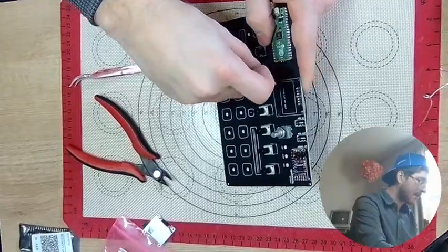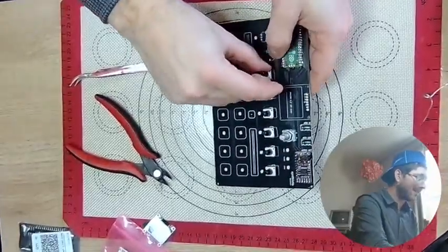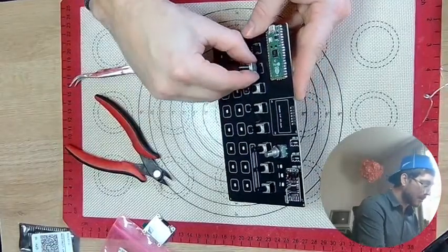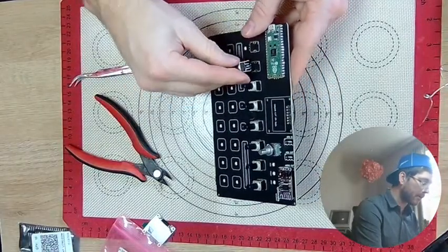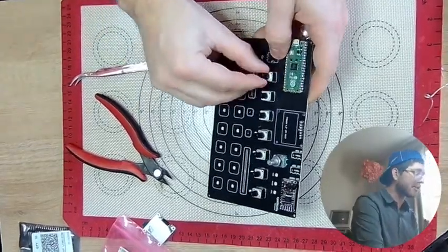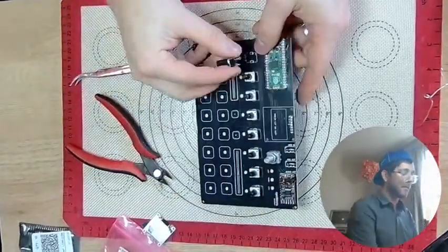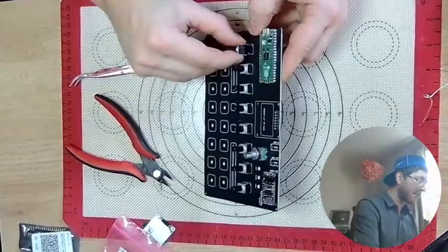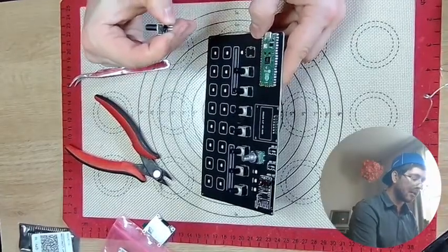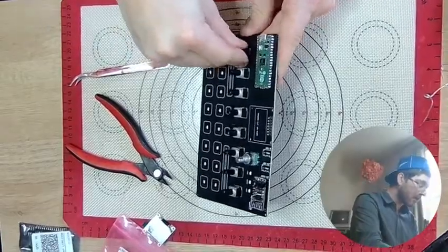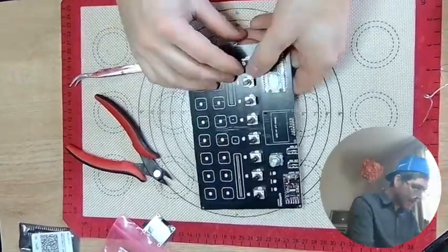In a way it's easier than through hole, because you don't have to flip the board over, bend legs, or clip after. If you have to solder 10 resistors, I would rather do 0805 SMD one at a time than through hole eighth-watt. That'd be so much easier.